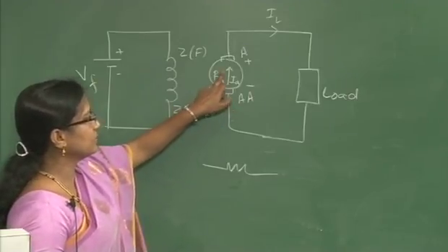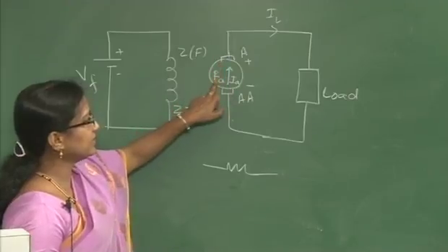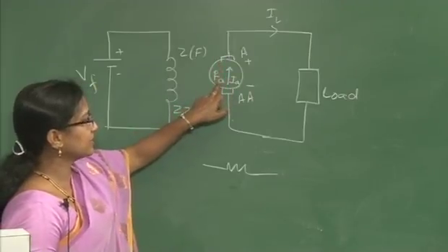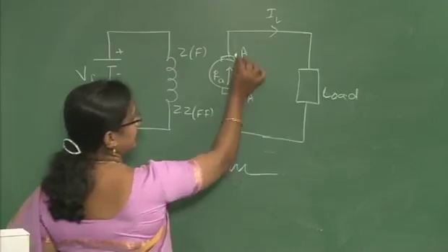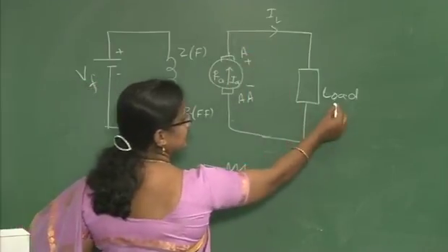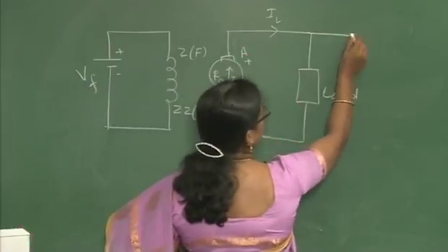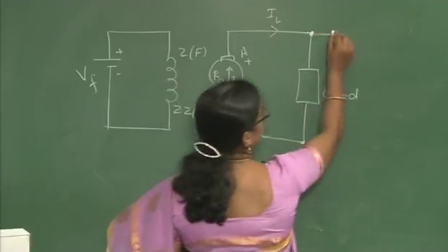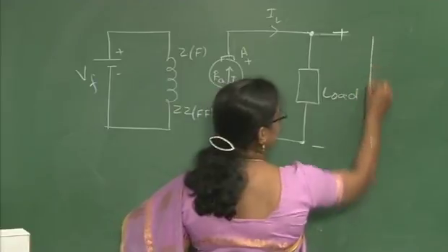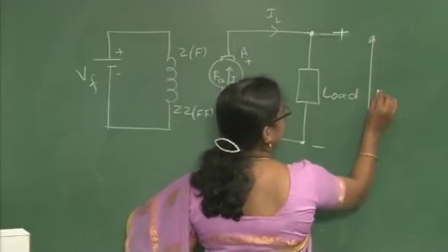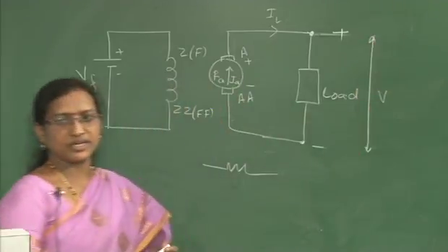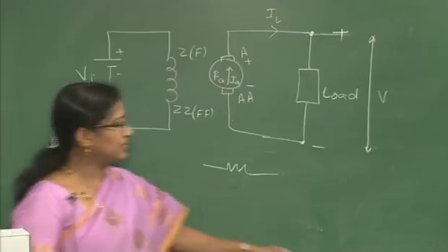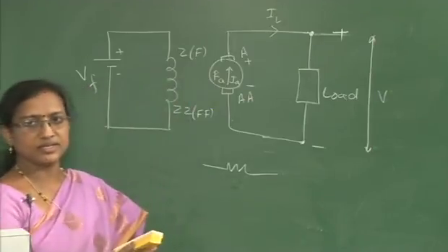So this represents the internal resistance of the armature, that is the armature conductors. So, the current Ia is flowing in this direction, this is the load. Then in this case also these are the terminal points, and the voltage across these terminal points you are going to consider as V. So, this is the equivalent representation of the separately excited DC generator.